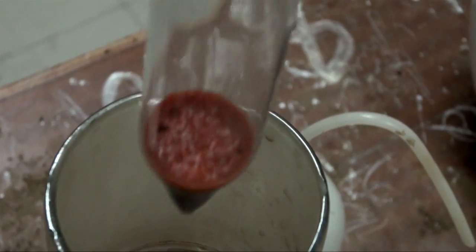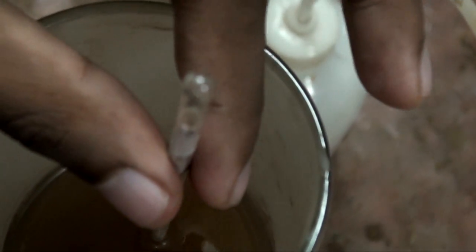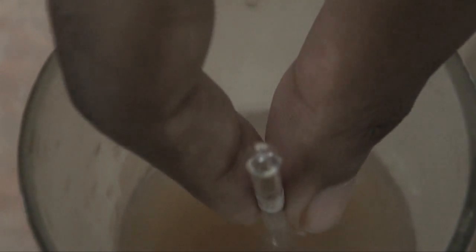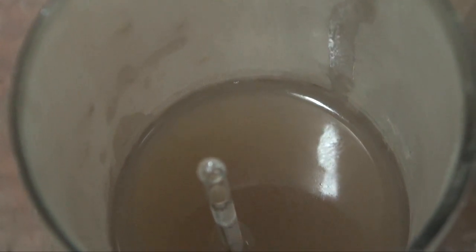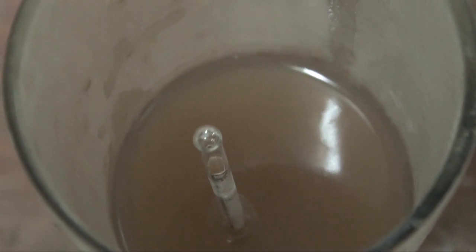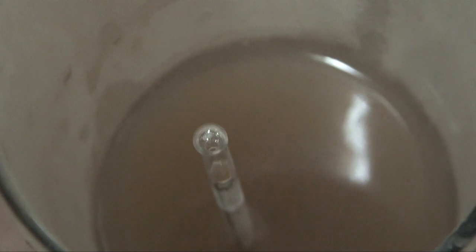So we go for an indirect method to quantify particle size distribution, and that is the hydrometer method. The basis of this test is Stokes' law for falling spheres in a viscous liquid. Grain diameter can be calculated from measurement of distance, time of fall, and density of the suspension.